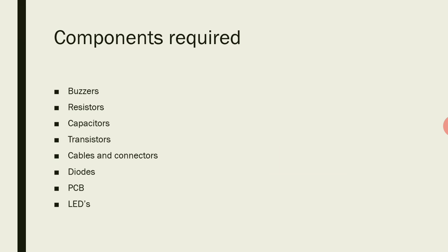Another advantage over them is the way of indication. Actually, the rotor and fluid indicators use a two-color indication to inform the short circuit event. The two colors are black and red. Black is displayed in normal conditions and the red is displayed when the short circuit event is occurring. But in this short circuit indicator, we are using a buzzer too, which helps us to a great extent to detect the short circuit and take necessary actions immediately.